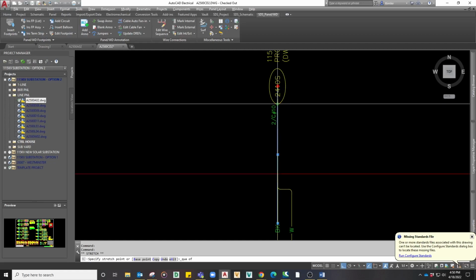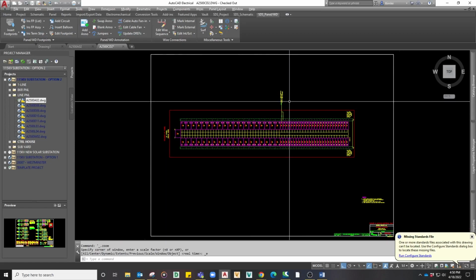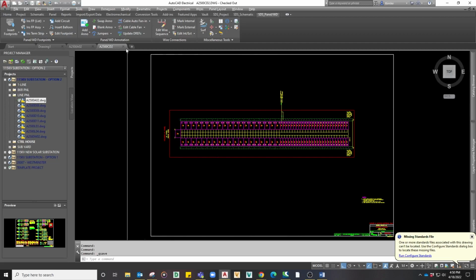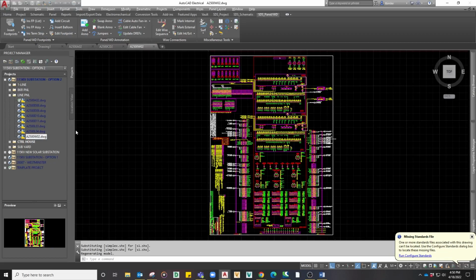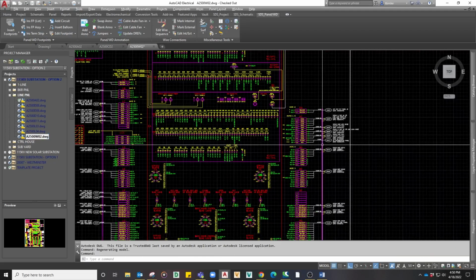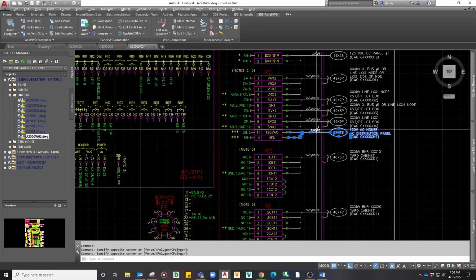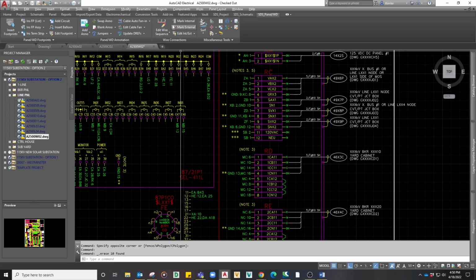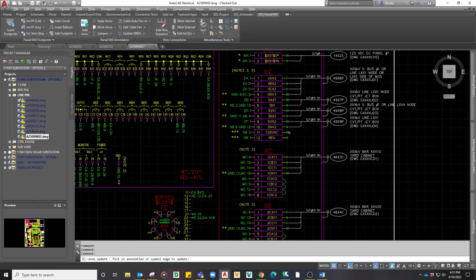I'll go ahead and correct this drop in real quick. Now it's off to the wiring diagram to draw the other end of the cable off of the RC terminal strip. Go ahead and delete the stencil layer. Under the SDS Panel WD tab, I'll select Anno Single Pick, keep the defaults, and go ahead and select both RC11 and RC12.